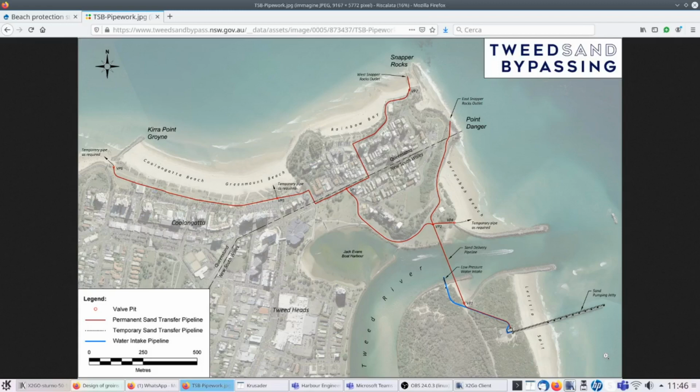If you look at the color of the sea offshore, you can see a kind of clearer stream offshore, which indicates the trajectory of the sand after building these walls. And by stopping the longshore sediment transport, these walls avoid the formation of the bar.